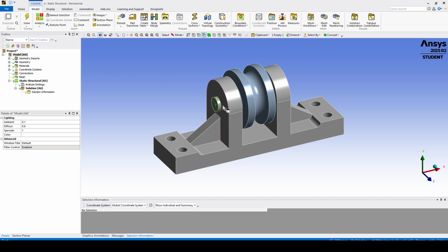Once the model is imported into a simulation tool like Workbench here, the next steps usually include the following: assigning material properties, generating contacts, generating a mesh, and applying loads and constraints. Finally, you run the simulation. We won't go deep into simulation here, but it's important to understand how your model is used. So I will try to describe every step a little bit.